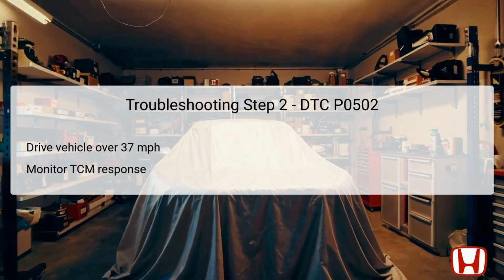As the vehicle accelerates, the sensor will generate pulses corresponding to the revolutions of the secondary driven gear. Observing the TCM's response at this speed is critical, as it will indicate whether the DTC P0502 is still present or if new diagnostic information arises. Ensuring that the vehicle is driven safely and in accordance with traffic regulations during this step is paramount for both safety and accuracy in the diagnostics process.